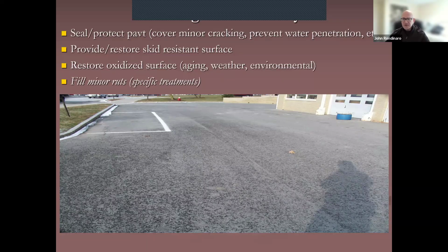The surface is uncracked. It's starting to show a salt and pepper look just after it's rained and there's moisture on the surface. That means moisture is being absorbed into the pavement section, and it's time to get a coat of paint on top.